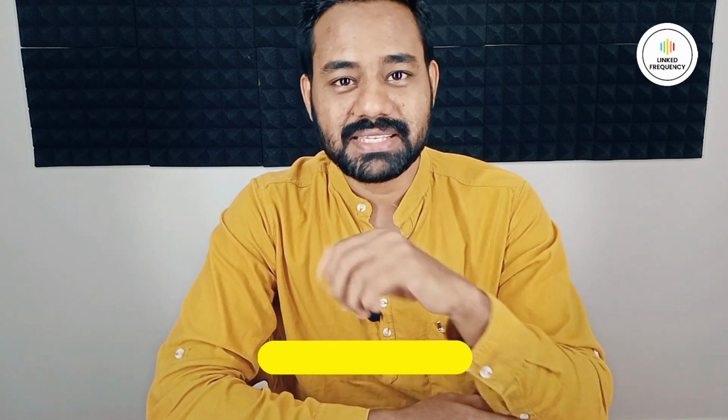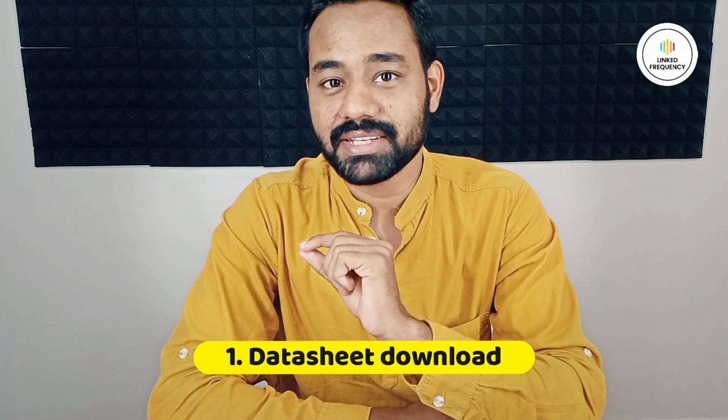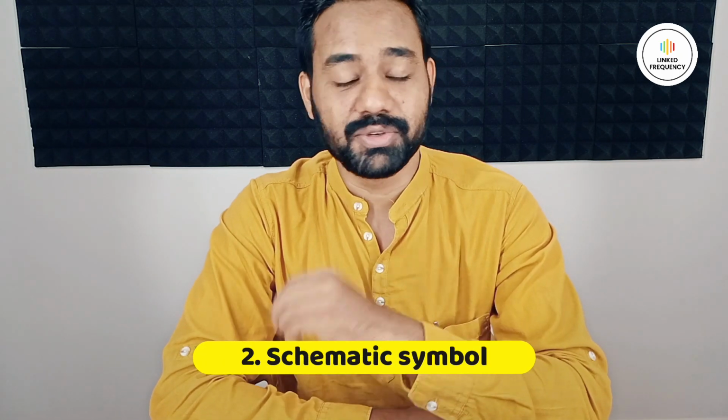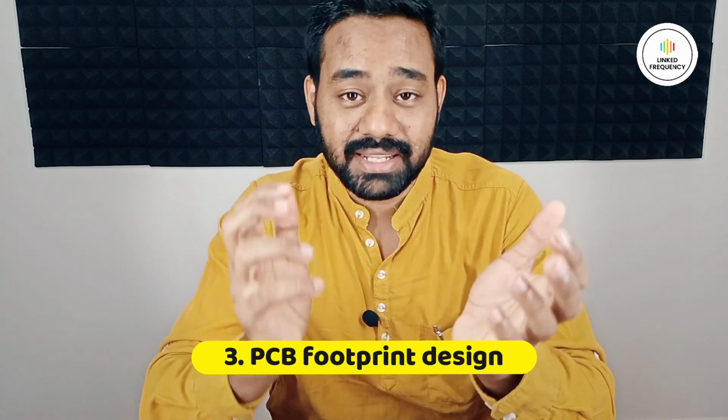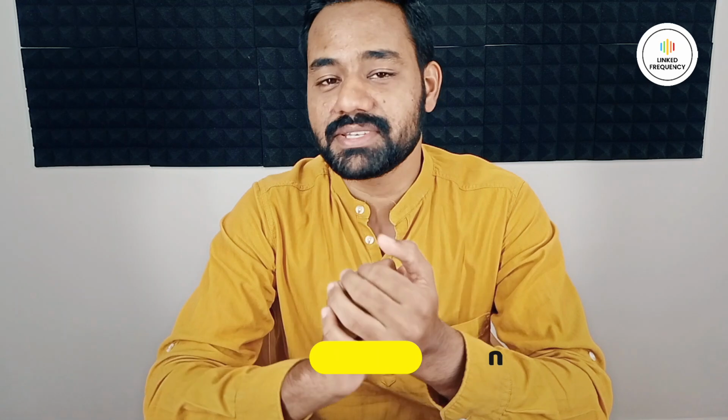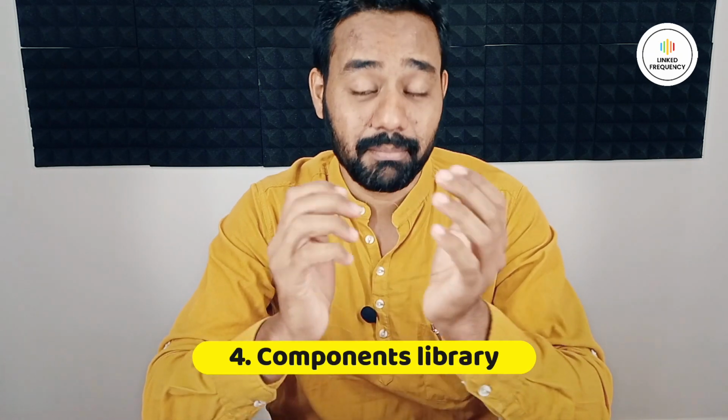This video is divided into 4 important parts. First one is understanding and downloading the right datasheet from the manufacturer website. Second step is to create a schematic symbol using IEEE standards and user friendliness or user interface as a priority in EasyEDA. Third step is creating a PCB footprint following IPC standards and also a Cartesian geometry in EasyEDA. Last but not the least, the fourth step is to combine the PCB footprint that we have designed with the schematic symbol and make it a component library so that you can use it in your future projects.